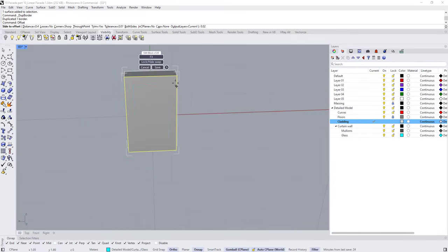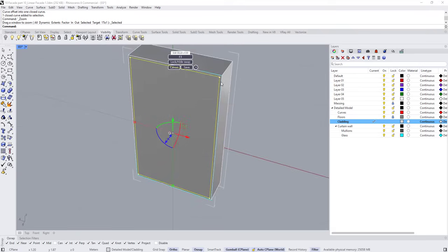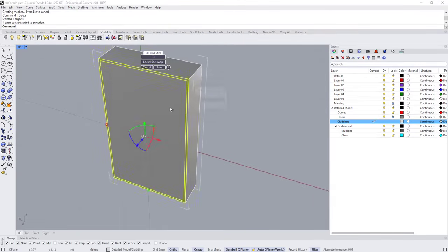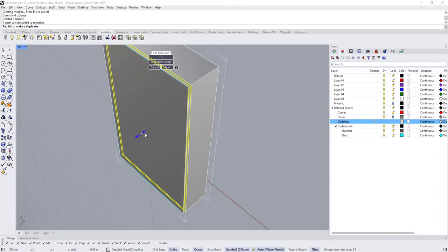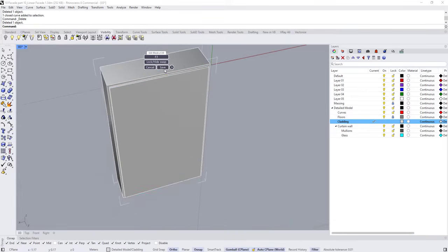We have values of 0.02, 0.05, and let's create a loft or maybe a surface here with this curve. Select this surface and let's extrude it by a value of maybe 0.05 and create Boolean difference. This one, right click, select this one. Let's delete these curves. Save.